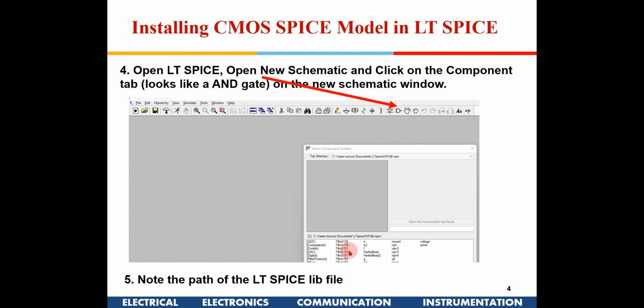These components come embedded in LTSpice. NMOS and so many ICs are there. Lot of things are already there in LTSpice, but we require the TSMC CMOS, and NMOS is not there. We want that. So that's why you click that, and you will see lot of components here.